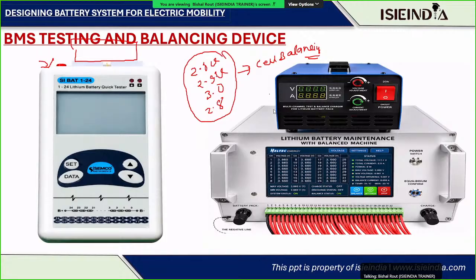For that, we need to connect it to the cell balancer. So this is the cell balancer. This is called an active cell balancer, and it balances the cells by using a capacitor bank. There is another kind of cell balancer, which is called a passive cell balancer.